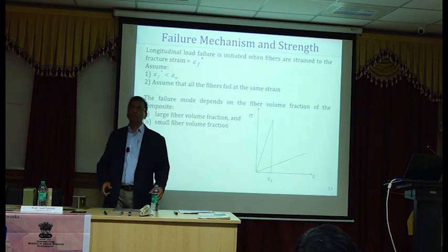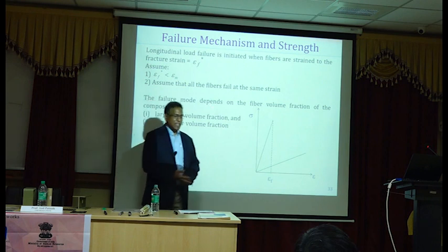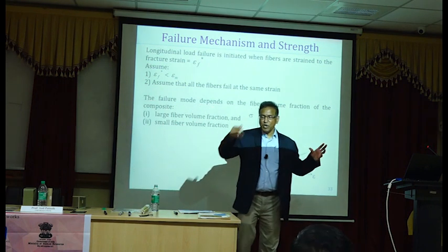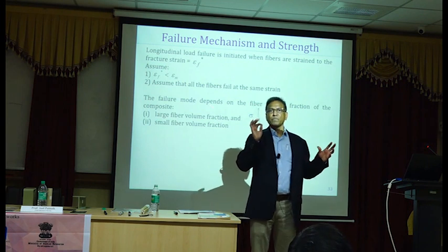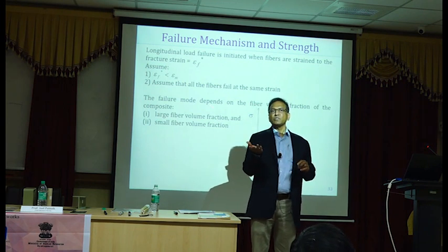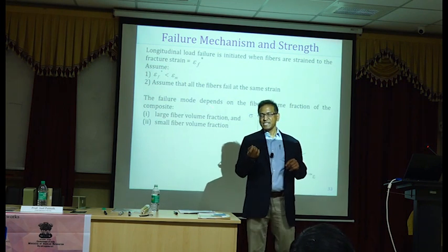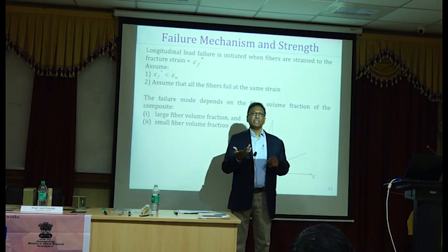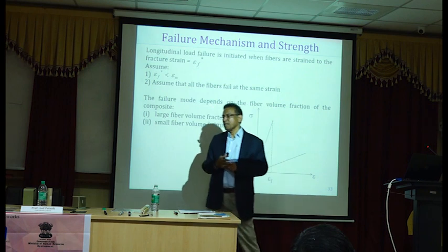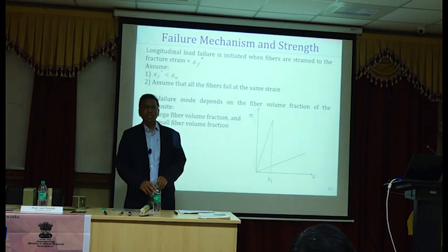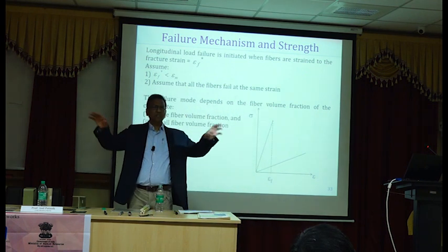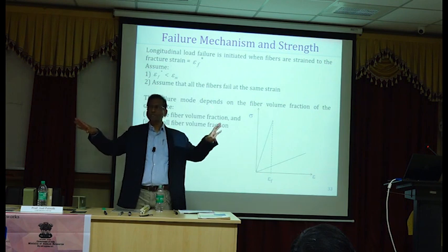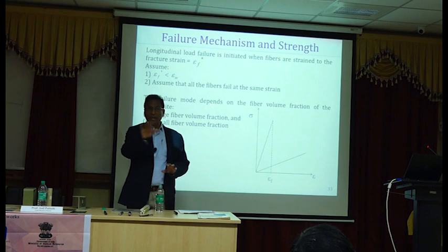So the reason you provide minimum reinforcement is, if you have a plain concrete specimen and you apply a load, it will fail at a certain point, which is also called the modulus of rupture, when the stress at the bottommost fiber is equal to the flexural tensile strength of concrete. It will become two pieces. No reinforcement, it becomes two pieces, right? So the code tells you don't let that happen.